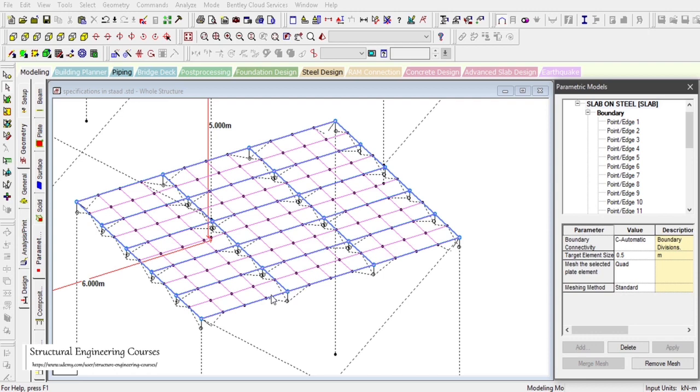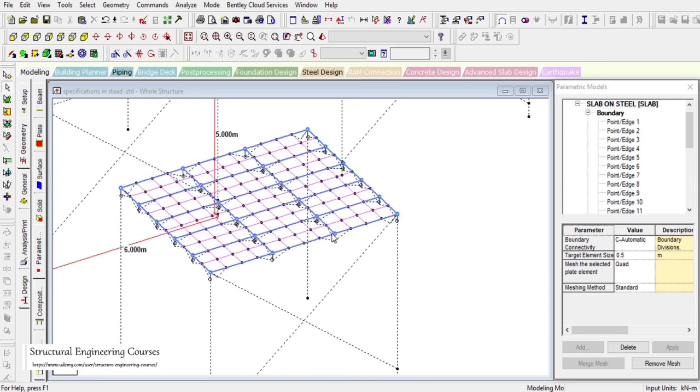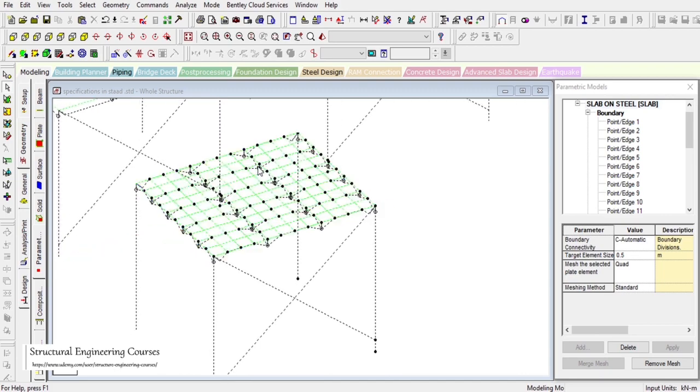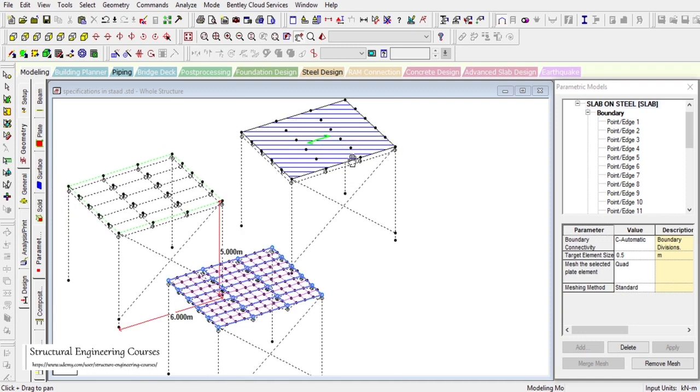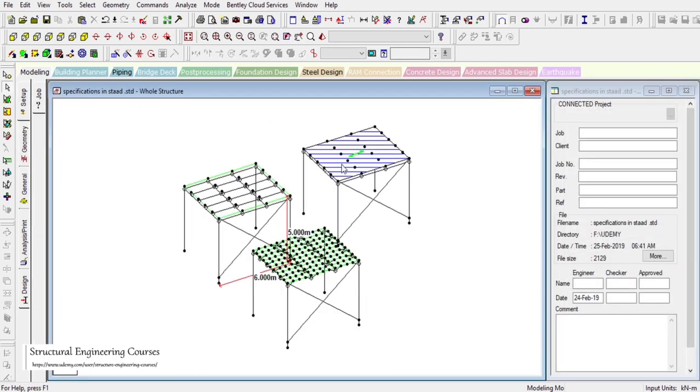And why is this whole thing going up and down? Because we have added the specifications. If we want to correct this structural steel arrangement, we need to do the offset commands again. But this was just an introduction to show you how we can go ahead with two approaches. That is, this is the deck slab system arrangement, and this is the plate system arrangement with meshing. So we have studied both of these arrangements, and I hope things are clearer to you.